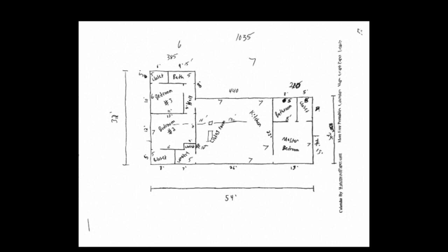If you look here, this is just a rough sketch of my layout of the house. Down in the very center by the living room, you've got these little boxes. That's where the unit's going to sit, and that's the return box and the output box on the other side. It comes out, then you've got your main trunk line. I don't know if you can see right there, 10-inch going back toward bedroom number 2, 12-inch going down towards the kitchen, and then right when we get to where the master bedroom wall is, it's going to reduce. It should reduce down to 8, but we're going to end up just doing 10.